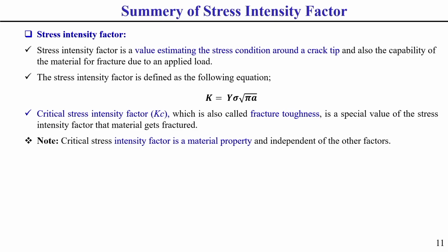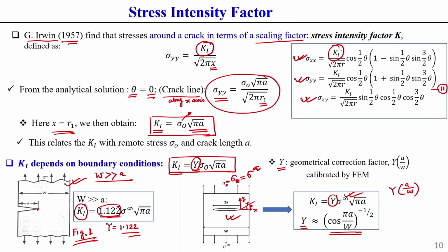So, what we can write: the stress intensity factor is generally a value which estimates the stress condition around a crack tip. I have already shown that around a crack tip, sigma xx, sigma yy, and tau xy are functions of K1. This you should keep in mind. In these equations, sigma xx, sigma yy, and sigma xy are each represented in terms of K1.